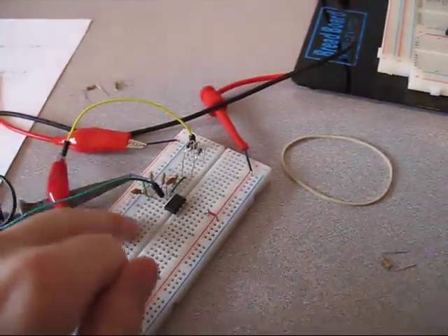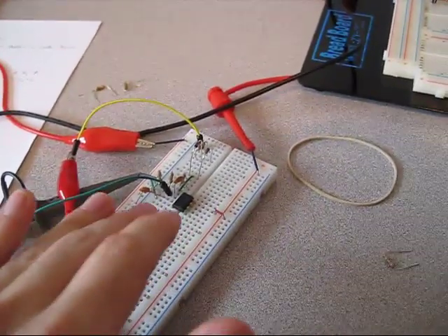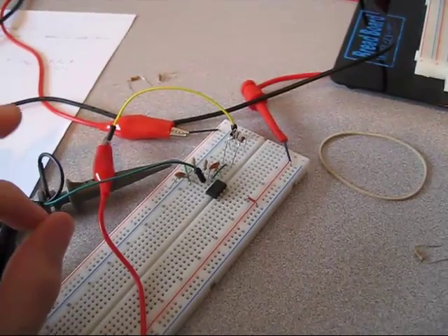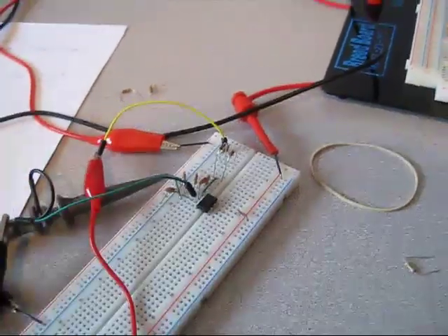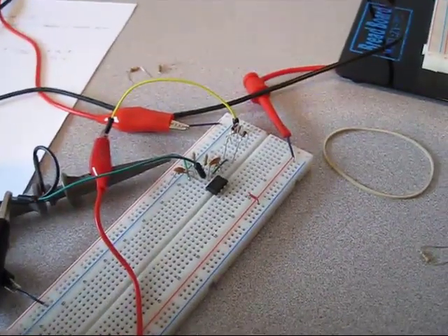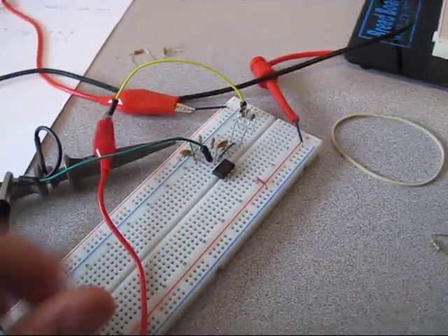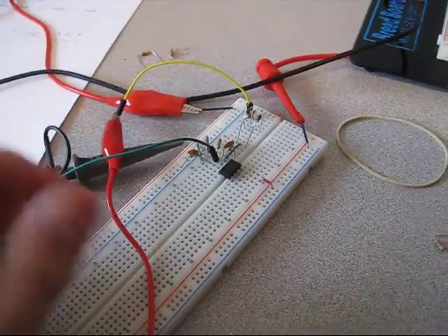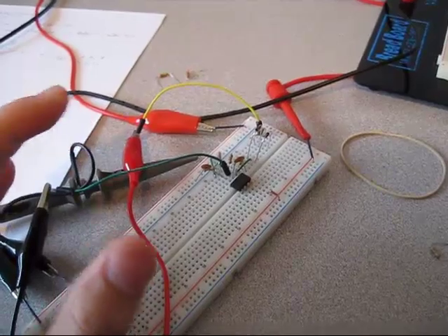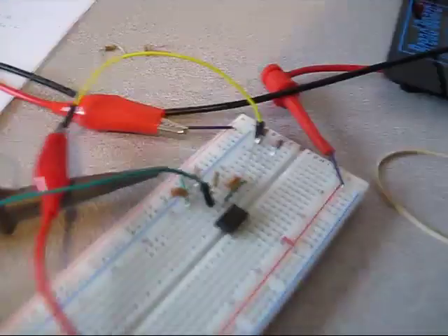So if you wanted to, you could also put in digital potentiometers instead of analog ones, and then you'd have to calibrate it with some actual analog trim pots, because digital pots have quite the percent tolerance from one to the next. It's a couple percent. I feel like it's like 3 or something percent. Let me turn off the power supply.